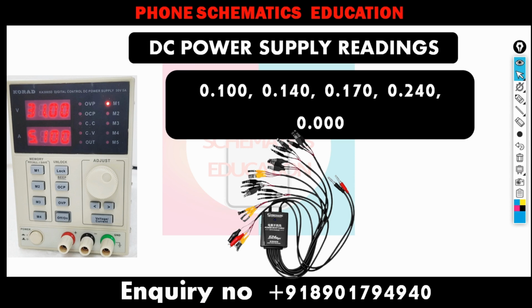So, a DC power supply reading. The first one: when you set the DC power supply and connect it with the motherboard on the battery connector, it boots up 40, 50, 100, 140, 170, 250. When you release the power button, after that it goes back to zero, right?